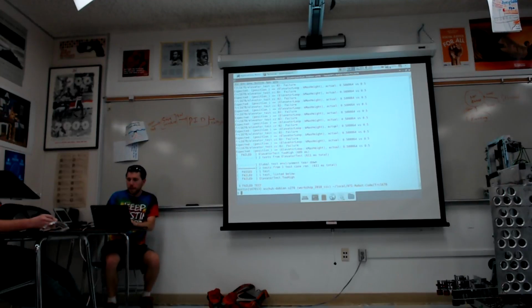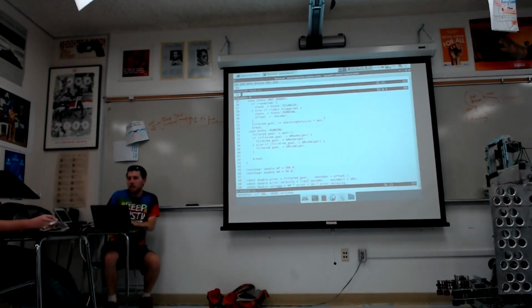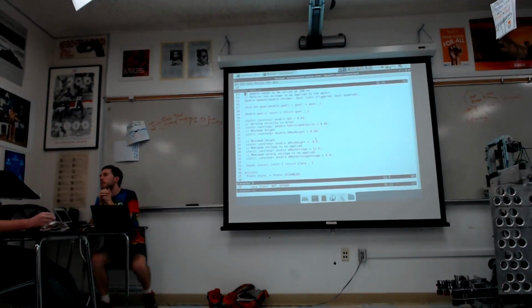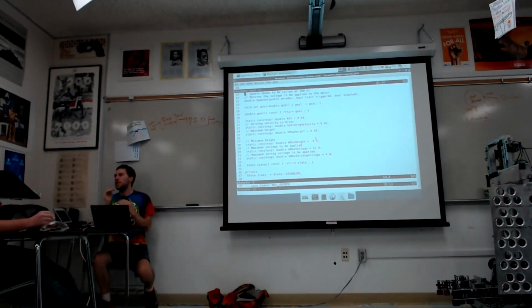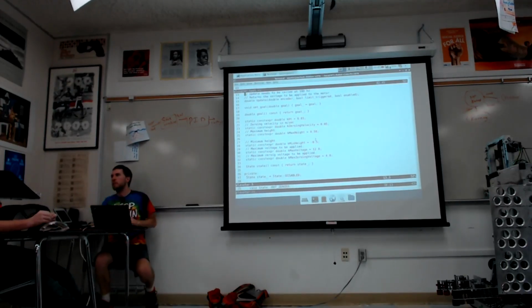Okay. Yeah. So the concept I like to use here is we have a hard stop and a soft stop. The soft stop is the max you'll let it go in software, and the hard stop is where the physical limit is. And you make them a little bit apart.